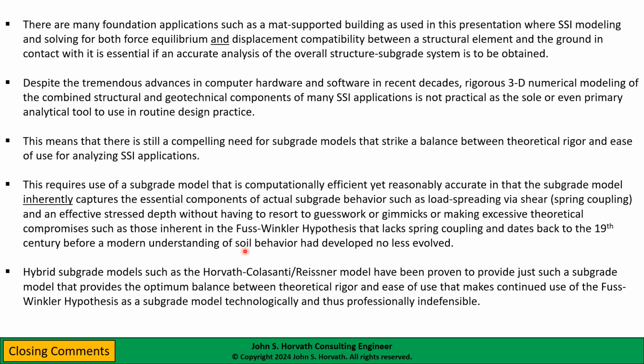So this Horvath, Colasanti, Reisner hybrid model, we've proven it. Again, this is not just a research concept. We've used it on actual case histories to show that it's a very practical subgrade model to use. It strikes that sweet spot, that optimum balance between theoretical rigor and ease of use.